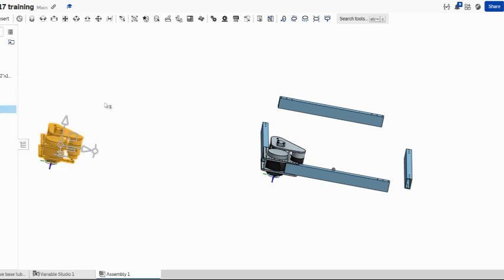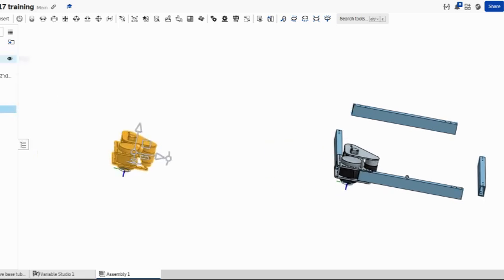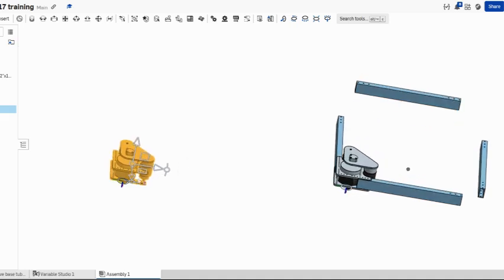So if I take that swerve module, if I click it in the assembly, here's my arrow, so I can click that and rotate it. And if I just start rotating it, I can then type in how many degrees. So now I've got it rotated 90 degrees.